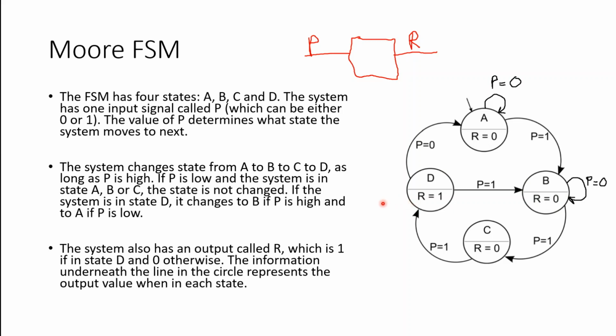Now, these Moore machines are typically the easier ones for us to deal with. If in an exam we are asked to draw a state machine, a state diagram, or some FSM for a particular system, this is typically the paradigm that we will use, the Moore machine. That is not to say that we will be limited to Moore machines. If we have a better understanding of a Mealy machine, that is also applicable. We look at both of them when we're looking at the past papers to see how these are drawn in an exam.